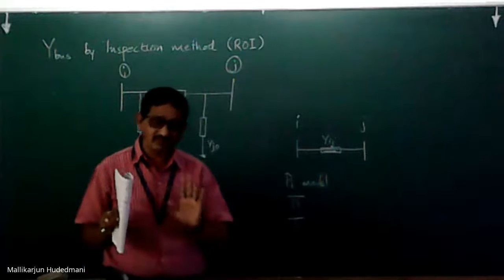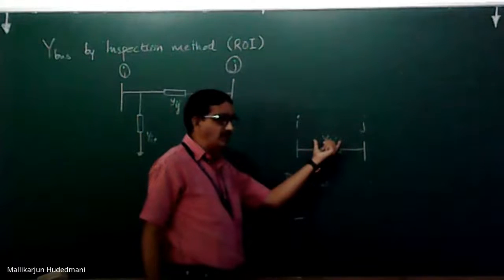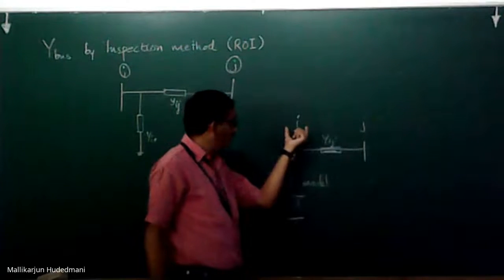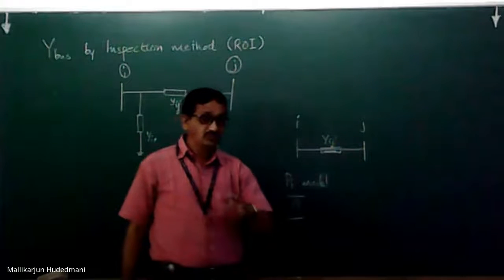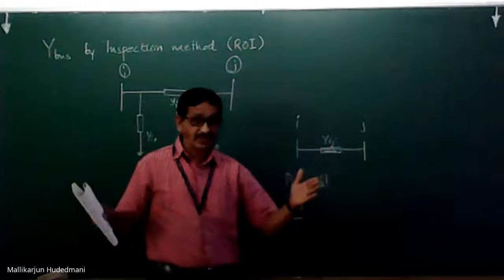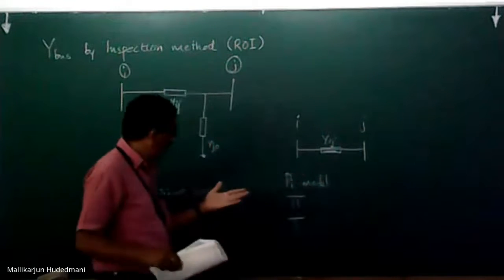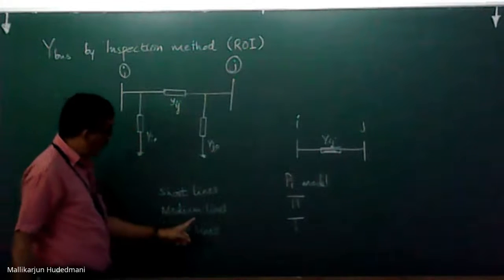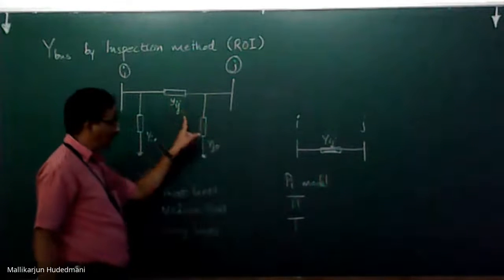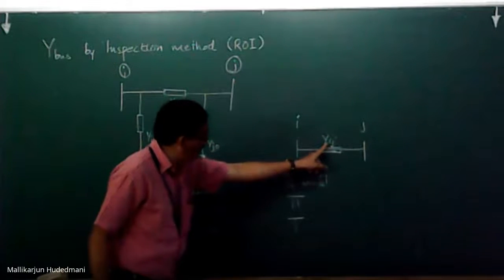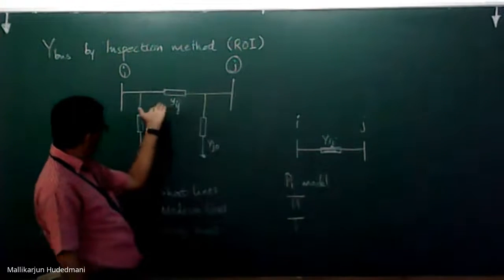For us, let us say very simple. If a transmission line is represented as Yij, an elemental admittance of a line between bus I and bus J, this is to say a lumped model. Suppose the line is a medium line by category, 80 km to 160 km range, then modeling may go by a pi or pi section. If it is a pi model, a particular transmission elemental data Yij between bus I and J, set to be in a pi model, would look like this.